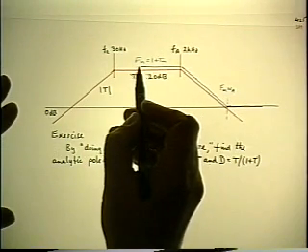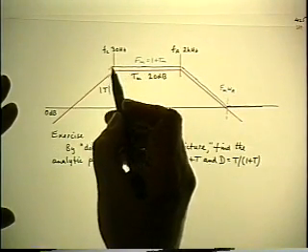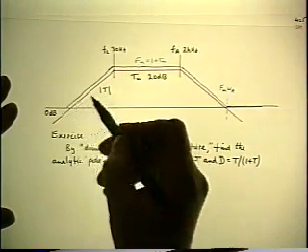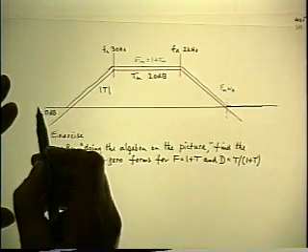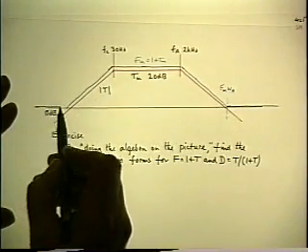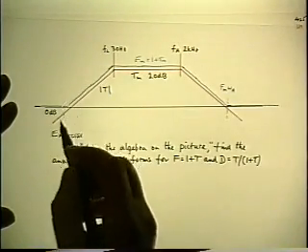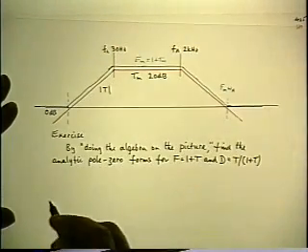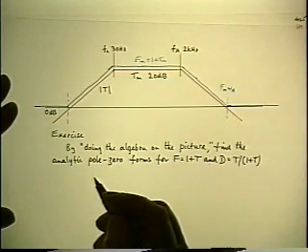So going down in frequency, the 1 plus T will have the same corner as the T, and that will continue parallel with the T until when the T drops below 0 dB, 1 plus T again will level off at unity or 0 dB. Extrapolate the asymptotes as before, and label the intersection with the appropriate frequency using gain bandwidth trade-off again.